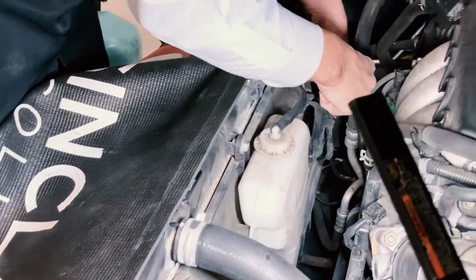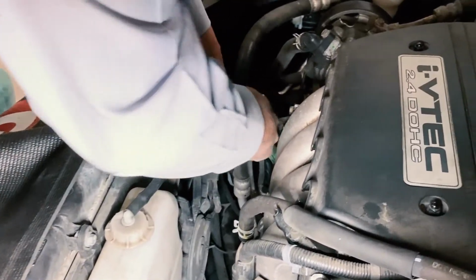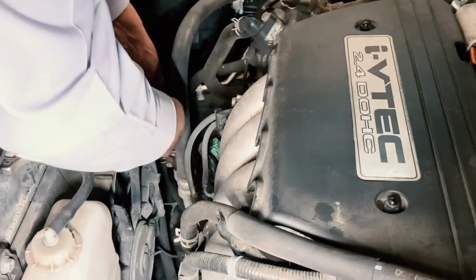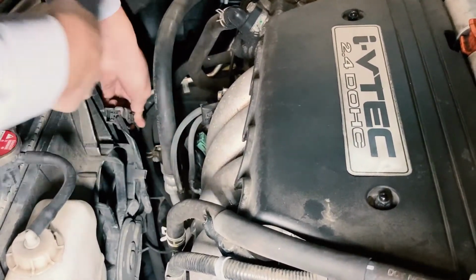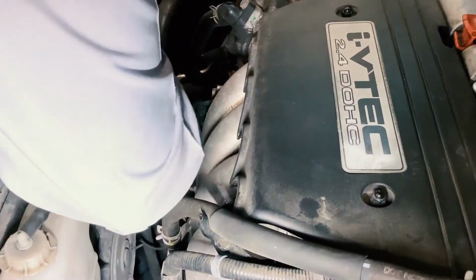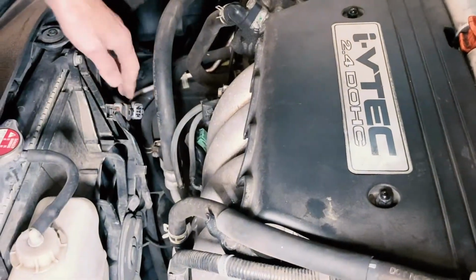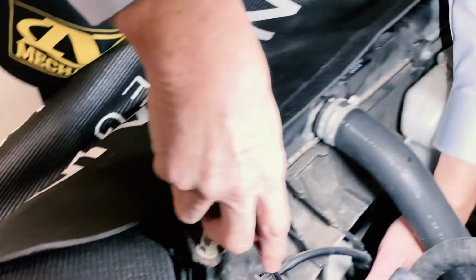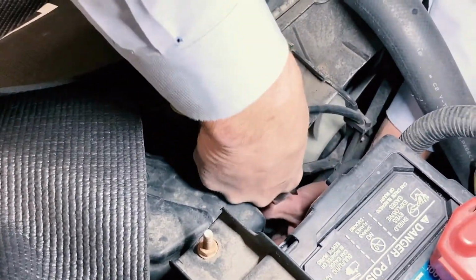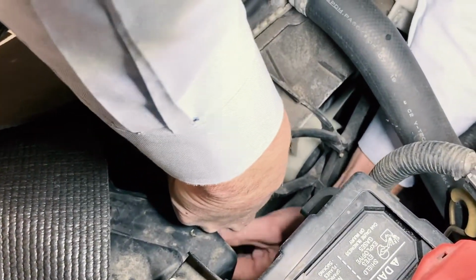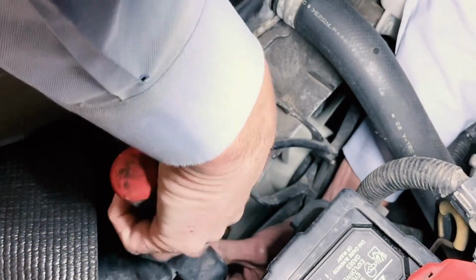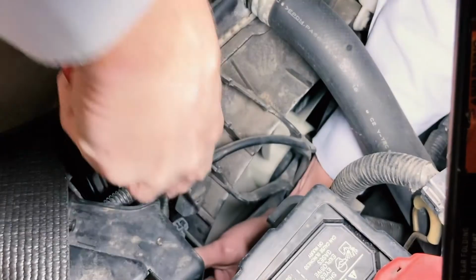So I'm going to come down here, use my screwdriver to depress my lock tab, and we're going to try to get this to unplug. Give me a second here to get that unplugged. So that one's disconnected. We're going to come over to this one, depress the locking tang, and see if we can get that to work free. And that should come out.